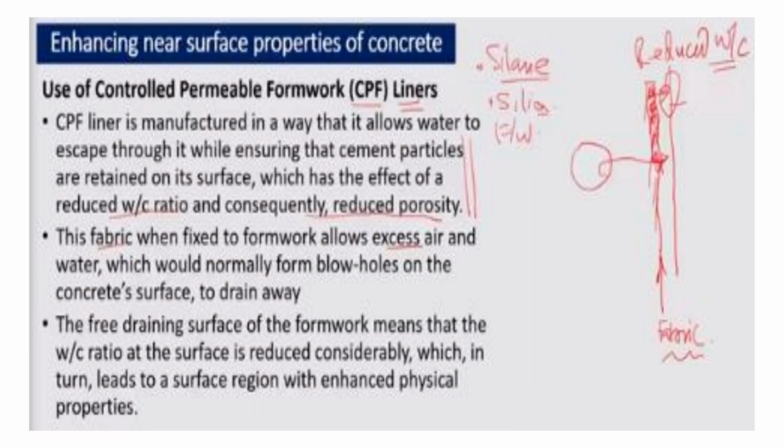So that is the second. First was the silane, second was using microsilica. These were the materials which could enhance the near surface property. Let us see the third way. It is by using CPF liner. CPF is nothing but controlled permeable formwork liner.